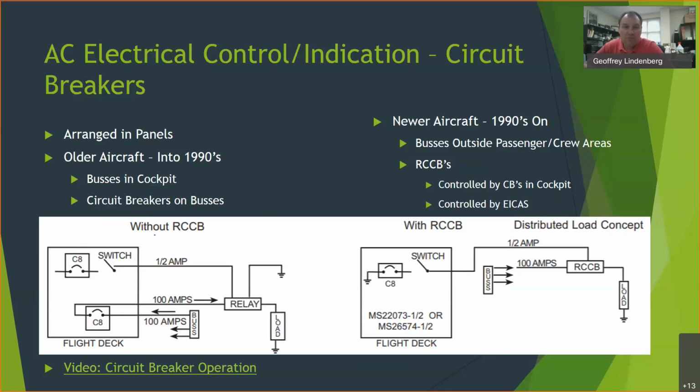But the one behind the flight engineer, for instance, has a lot of current running through it. The main current for the buses comes up into that panel. And so you have cases where you have this diagram, what's shown here on the left. A good example of this is the hydraulic pumps. So in the 727, they're wired like this.